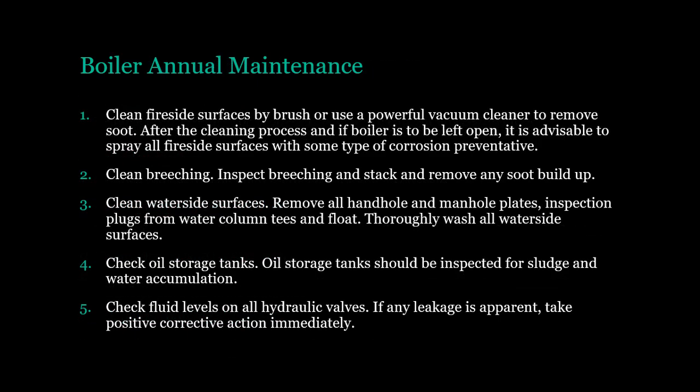Boiler annual maintenance. Clean fireside surfaces by brush or use a powerful vacuum cleaner to remove soot. After the cleaning process, and if boiler is to be left open, it is advisable to spray all fireside surfaces with some type of corrosion preventative. Clean breaching. Inspect breaching and stack and remove any soot buildup.